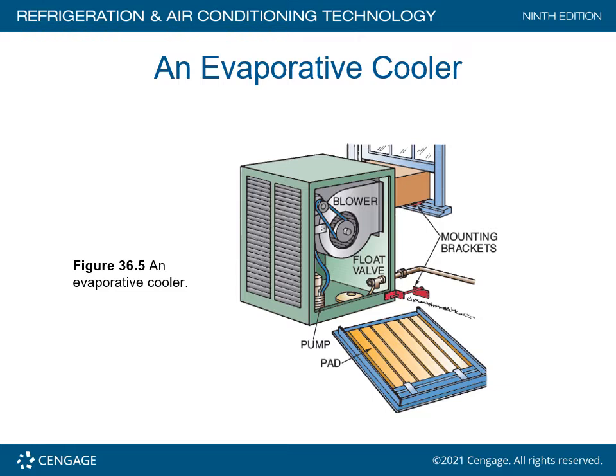Here we'll have a pump, which takes the water that's collecting in the tray here in the pan, and it's pressurized and brought up to a distributor, and the water will basically drip onto the pads here. Okay, swamp coolers must be maintained. Swamp cooler pads need to be changed out a minimum of once every season. This system has to be cleaned up.